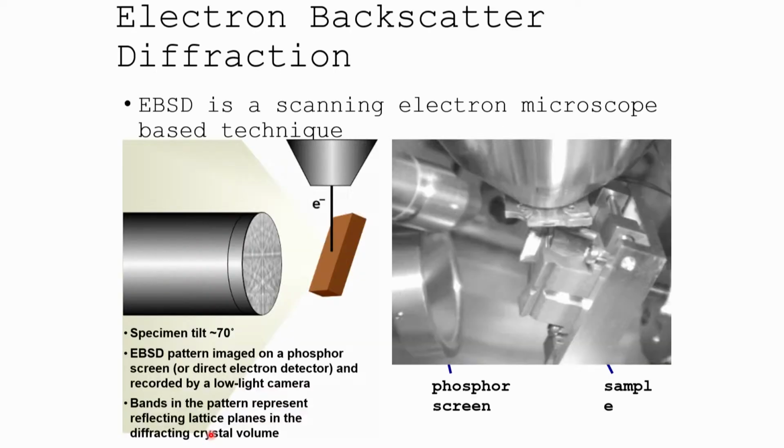All right. In addition, electron backscatter diffraction. Now, if some of you know me or you've read my papers, you've probably looked at work I've done in electron backscatter diffraction. So when the technique first was commercialized in 1987, that's when I was a graduate student. And we bought a unit in 1987 to do electron backscatter diffraction. And it wasn't automated. You had to take an image, and then you had to do some measurements, and you had to click some buttons, and you had to tell it, okay, this is a 114 zone axis, and that's a 111 zone axis. And then it could come up and tell you what the crystallography of the material was. And it was manual. To begin with, I could do maybe 20, 30 measurements per hour, which is much better than if I had to develop the film like they started with, a decade before.